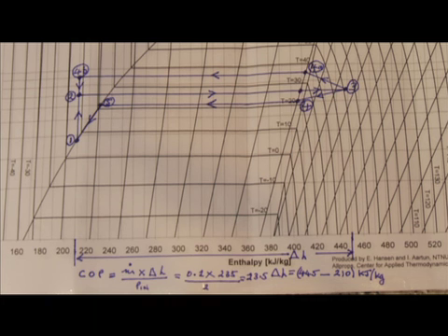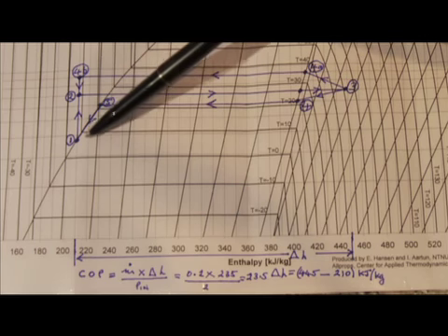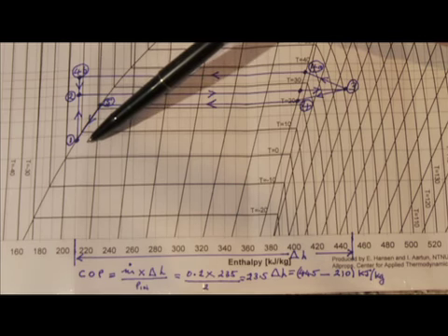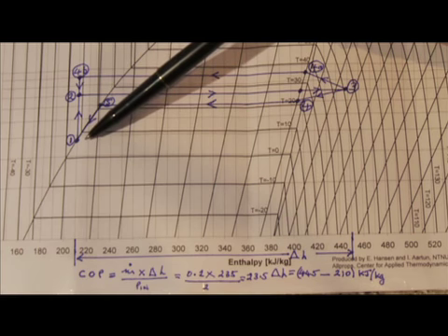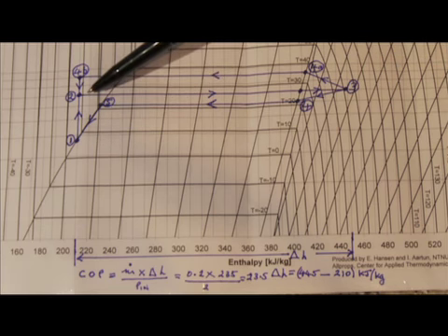In front of you, you can see a pressure enthalpy diagram. This is a plot of pressure on the vertical axis versus enthalpy on the horizontal axis. From the data logger, we've been able to produce what's called a pH diagram, which defines how the thermodynamic cycle works. And I'll just quickly run through that diagram with you. The first point 1 over here is the starting point, where we started just below 0.4 of a bar and the pump takes the pressure up to just around about 7 bar.